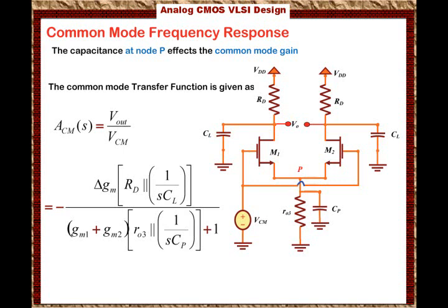So what's interesting here now is not only the gain a function of frequency for the differential amplifier, it is also the common mode gain, and that is interesting. The common mode gain is a function of frequency, which means that we will have a different response for the common mode gain, and the differential gain is a function of frequency as well. So keep in mind that what we're doing here is looking at approximations to understand the behavior of the circuit, but to get exact or more accurate results, you have to use computer simulations.